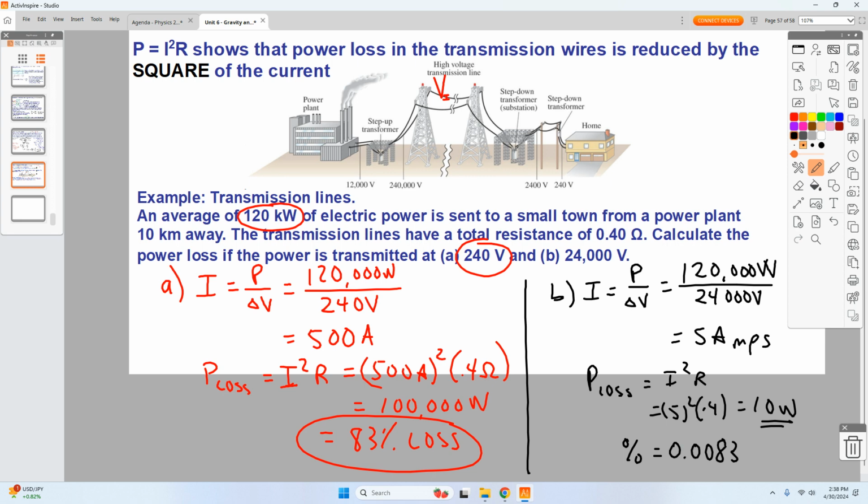Well, how much current flows through your body is largely a function of what is the driving force, what's the voltage, and how much resistance you have, right? So if you touch a power line that's at 24,000 volts, that's a lot of driving force. Even if you have a decently high resistance, you're still going to be hurt, right? So, all right, there you go.